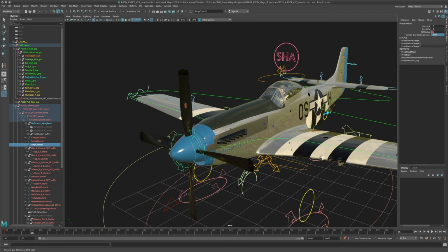So as I said, 2,700 rounds per minute, you really can't render that. It just uses a ridiculous amount of steps in between that have to be evaluated. So you have to find a balance and maybe do a few test renderings with different values at the beginning to decide what works for that kind of production. But that's something very specific for propellers.